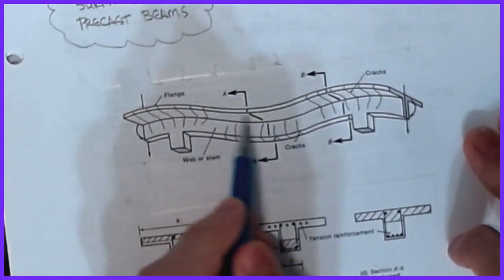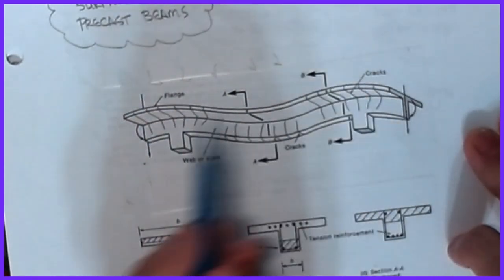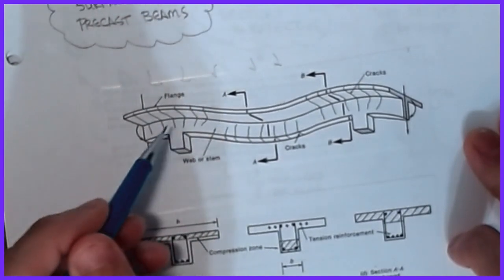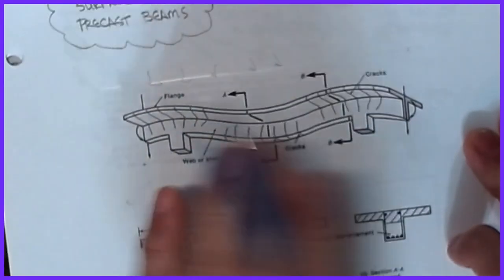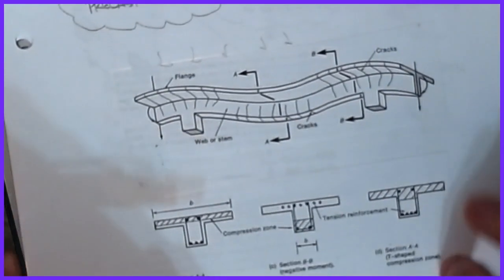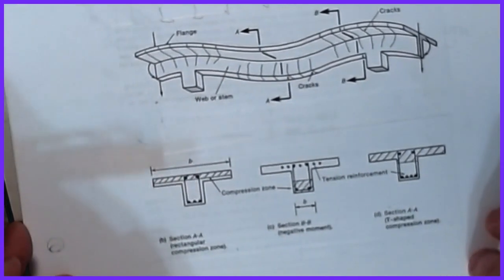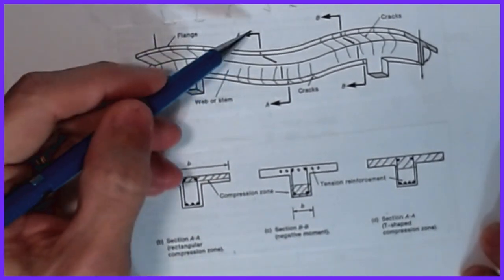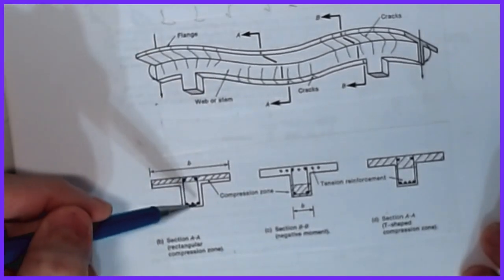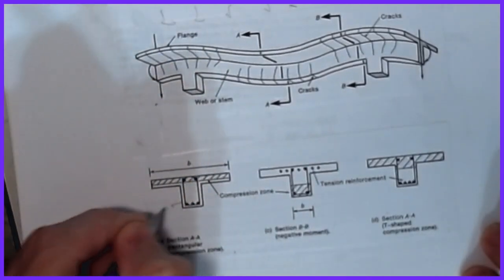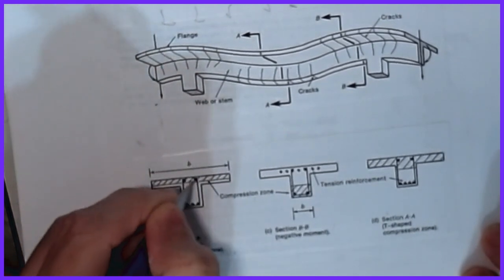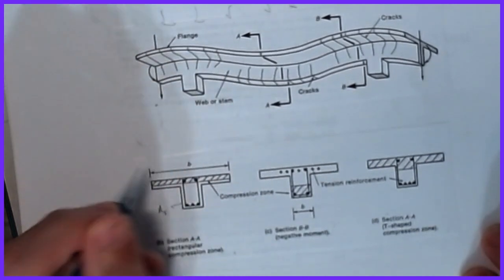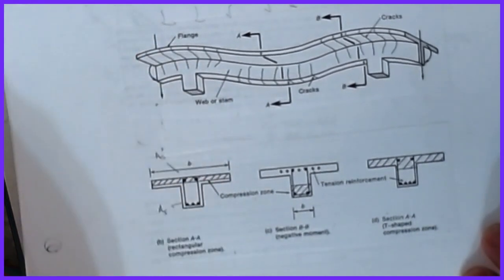Now, we haven't even talked about slab reinforcing yet and the requirements for that. Sometimes we can incorporate the reinforcing in the slab as being part of the reinforcing in the beam. But in this exercise, we're just going to look at how I analyze this for capacity. So I've got a couple of pictures here. And so what happens is, if I correlate back to our picture, I've got section A. This would be our reinforcing with the primary A_s amount here being located at the bottom, and then a couple of bars at the top, whether it's just to help hold up the stirrups or if it's actually being used for capacity, this would be some sort of A_s prime happening here.